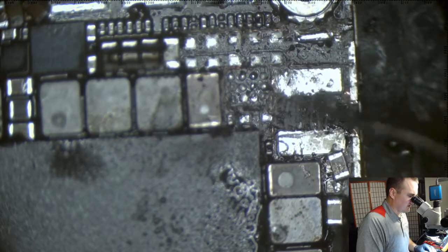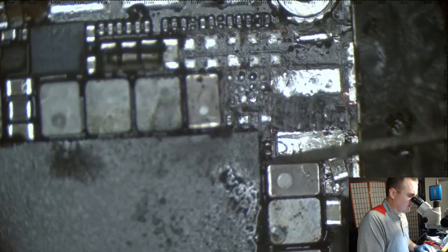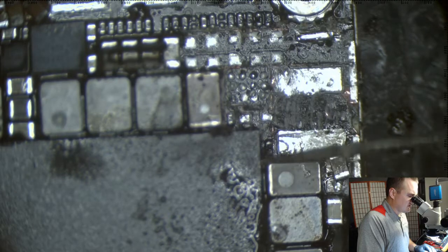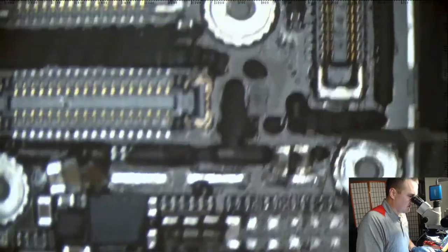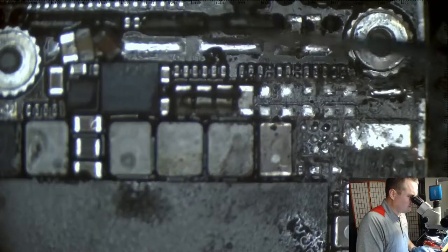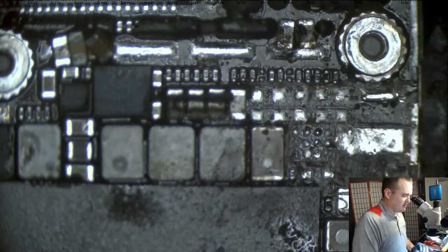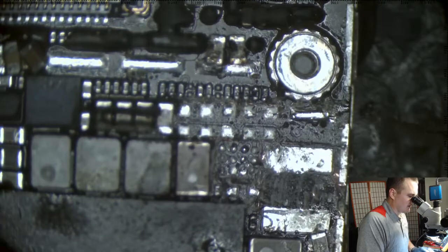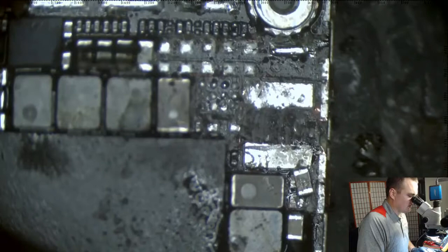I really don't like picking underfill. I know some guys, every time they do a touch IC, they come and pick all of this underfill out from the other side. Every bit of it. Because when you're doing a touch IC, if you get too much heat on there, you'll start reflowing through the board, through the other side. This is a two-side board. It's not that thick. So stuff will start reflowing all around it, all on the other end.